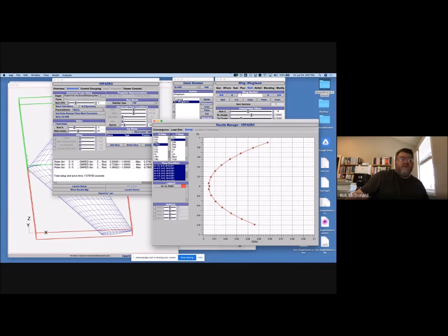the intercept of this polar, this lowest point, is what we call CD naught, CD 0. That's our parasite drag. This intercept is caused by the friction of the air on the wing and things like landing gear, right? So when I say that we double the drag, that means we take this whole parabola and we shift it to the right. We shift it big time over here to the right to get that CD naught up. Whereas the curvature, this parabola shape, that's caused by induced drag.